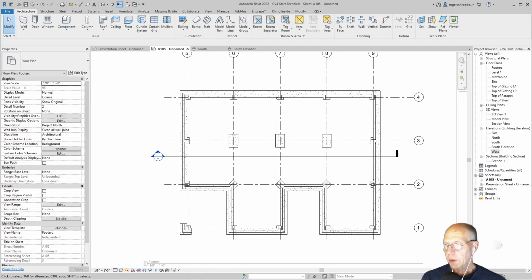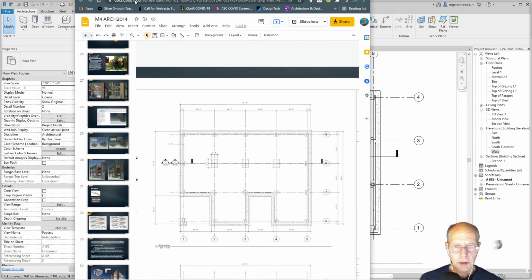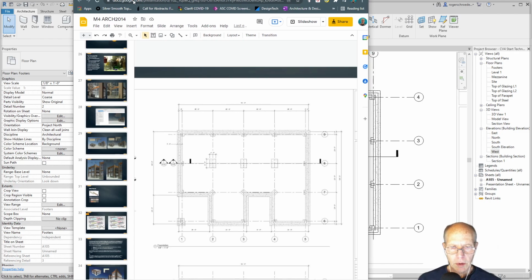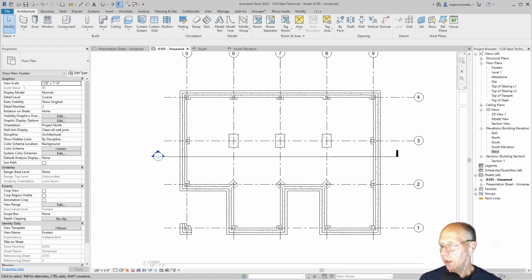Now, we're going to add a bunch of dimensions. Let's see if I can drag this onto the screen for you just for a second. We're going to add dimensions like this. I'm going to use this as the guide. You'll notice there are not a lot of dimensions, and one of the reasons is because everything else becomes kind of determined by the next thing. So once you determine one typical element, every other element is dimensioned the same way, and we avoid adding those dimensions if they are typical of other components that are similar. So we'll go through that, and you get the hang of it.